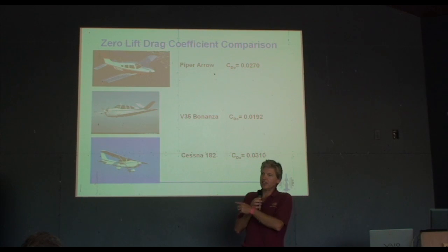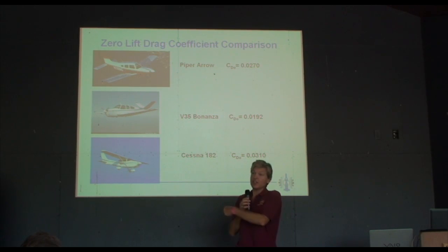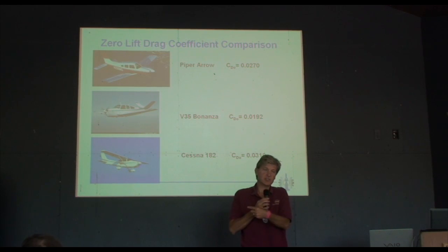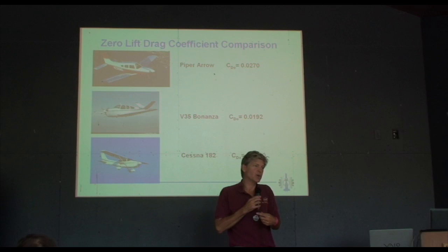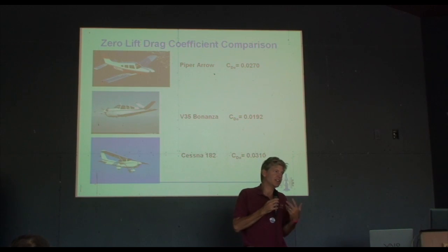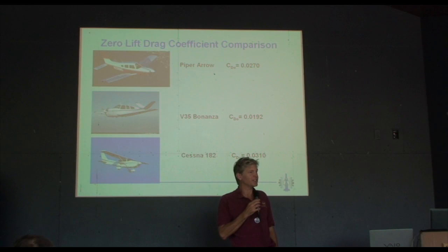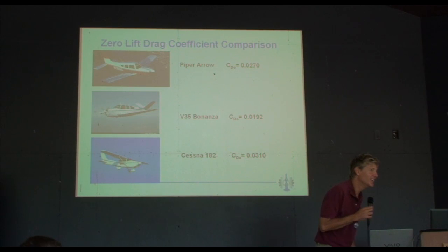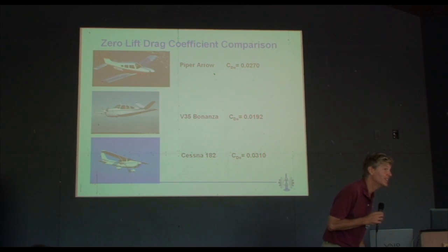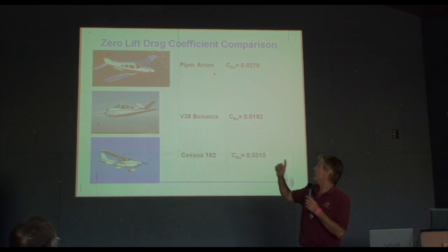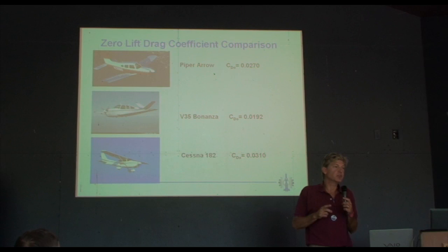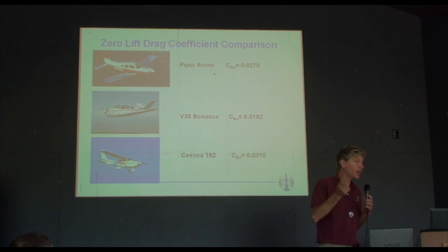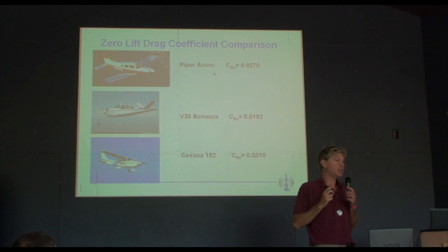And this is something that is really confusing to students, and it takes a while for it all to sink in, because it really does sound confusing. It's not just a bold number, yes. So that's for the whole airplane, not just for the wings. The CD0 takes into account the whole airframe, including the wing design. Yes, takes into account everything.